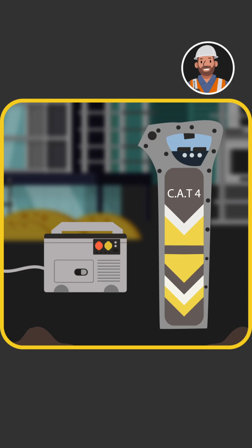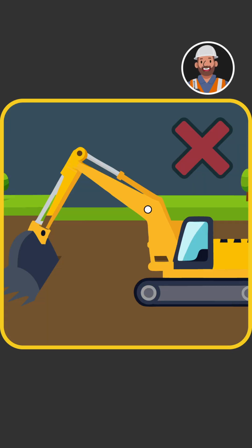Note: none of these modes can detect plastic, clay, or fibre optics. Always consider this limitation and use alternative methods to locate such materials. Starting work safely. Before starting any excavation, maintain distance. Never use an excavator within 500 mm of a suspected service.